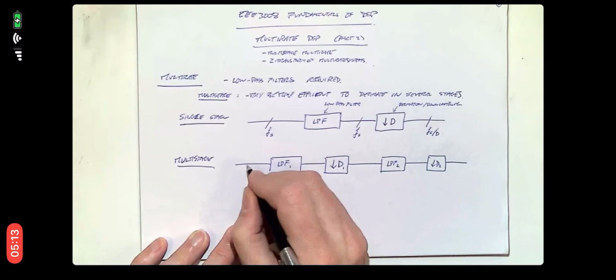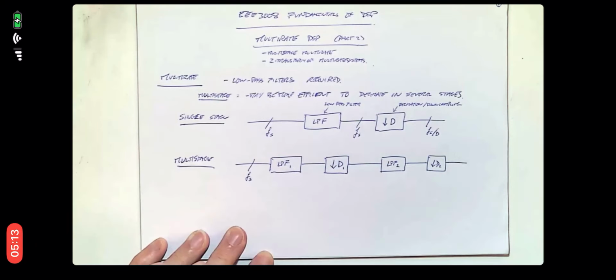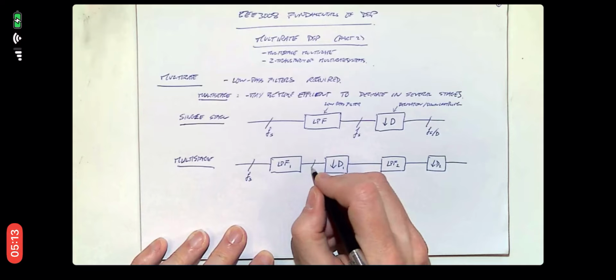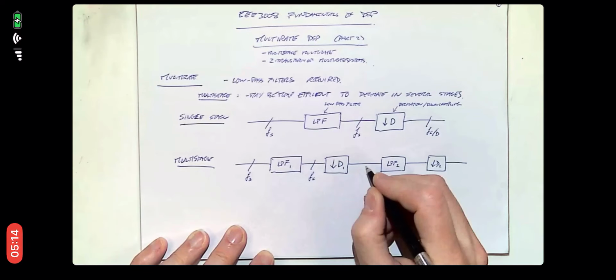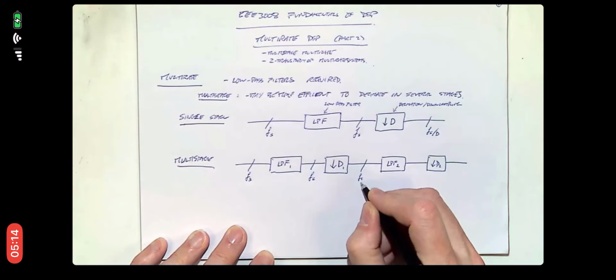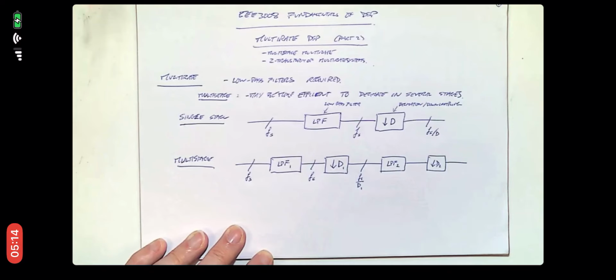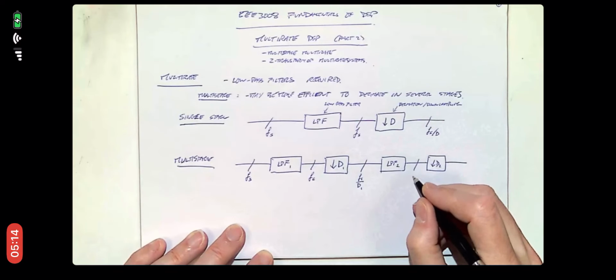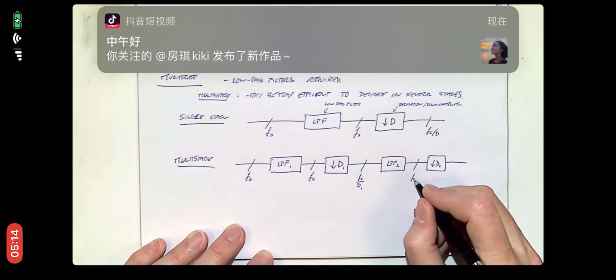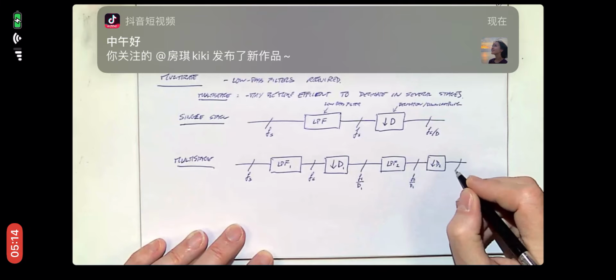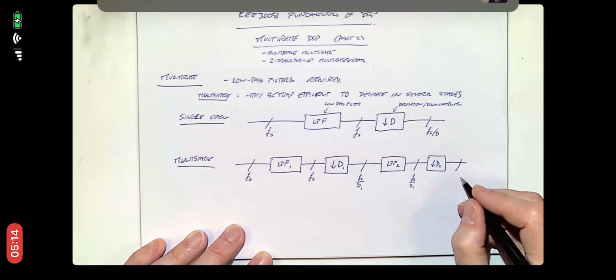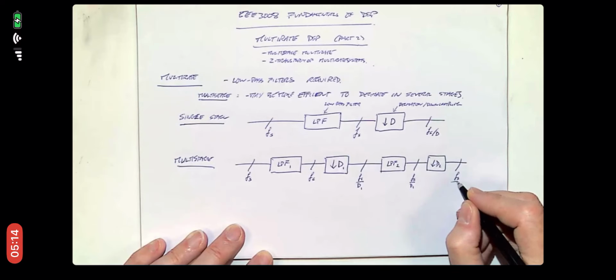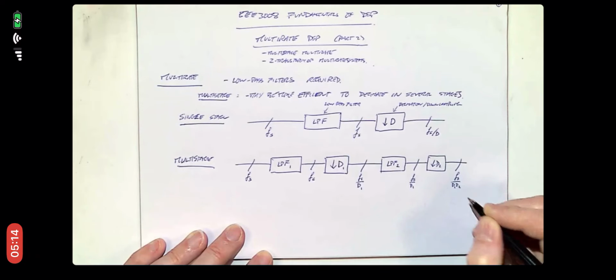So here we'd end up with our initial sampling frequency Fs, decimate by D1, so that's Fs over D1. And then the next low-pass filter, so we're still Fs over D1, and then finally, after also downsampling by another D2, Fs over D1 D2.